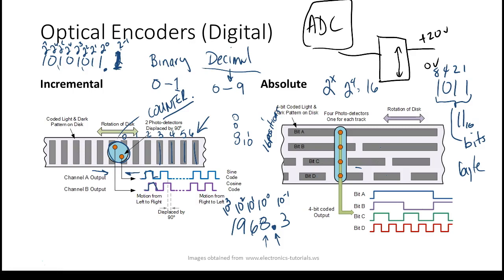So from 16 bits, which is 65,536, I add one more bit to the counter, then I can go up to over 1 million counts by using just a 17-bit counter.